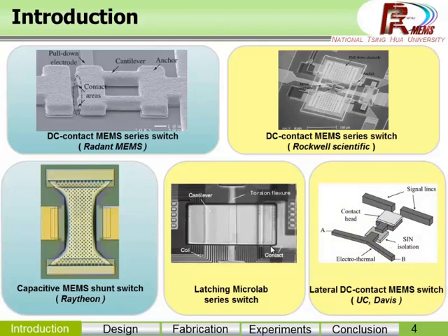Among them, the switch using electrostatic actuation facilitates the integration of MEMS and circuits, therefore advantageous to low cost, small form factor, less parasitics, and faster turnaround time, especially for consumer and portable electronics. Therefore, in this study, we are focusing on the contact switch of electrostatic actuation for the extended frequency range.